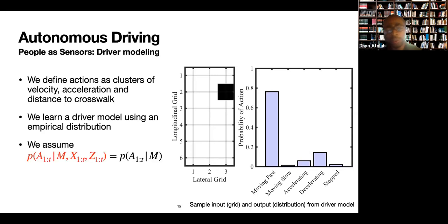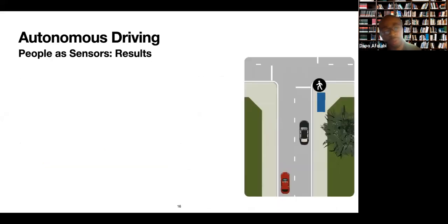Okay. So we make the assumption that, given the map of the environment, the autonomous vehicle's pose, as well as the sensor data obtained by the autonomous agent, is not important for predicting the behavior of other vehicles on the highway. And the reason why this makes sense is because, one, the relative location of the agents we're looking at. So usually the autonomous agent is behind the other drivers. Usually we're looking forward when we drive, right? So if we have a map of the environment, we're not looking backward and trying to say, okay, what is the autonomous agent doing? And we use that to make a decision. But one can also potentially incorporate some of this information going forward.